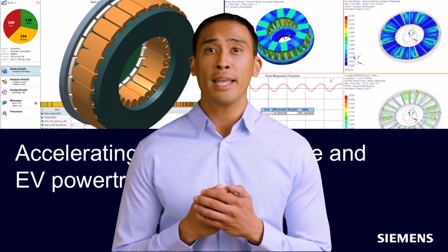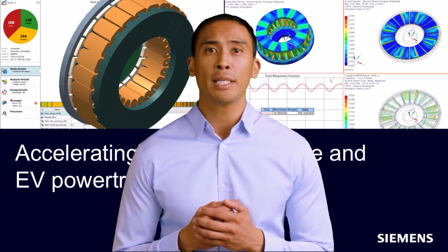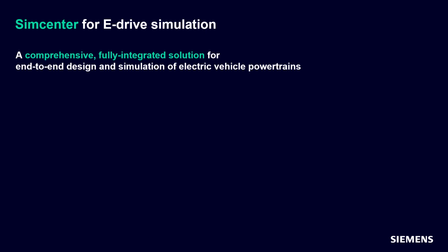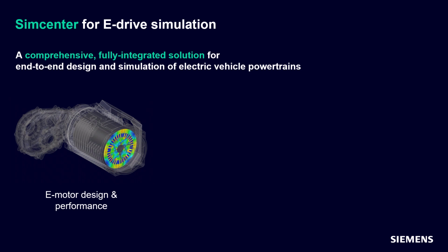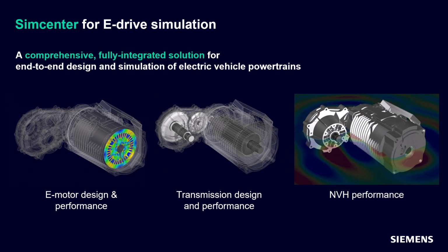Simcenter Mechanical solutions help you to develop your axial flux-based powertrain, from initial design through NVH verification. The integration of Simcenter 3D and Simcenter E-Machine Design provides the only enterprise software end-to-end workflow. First, you can rapidly search for the optimum axial flux machine design parameters, and then easily transfer the chosen design into an FEA solution. Simcenter automatically generates the motor geometry, sets up the air regions, creates the mesh, and more. You can then simulate performance for electromagnetics, structures, thermal, NVH, and more, so you can ensure your e-machine meets requirements.